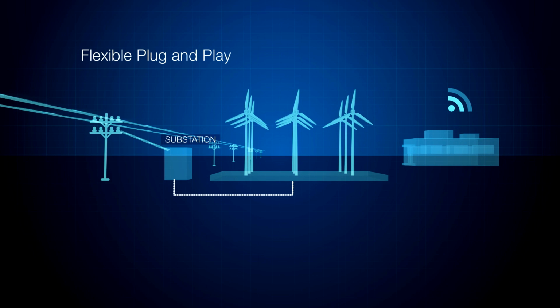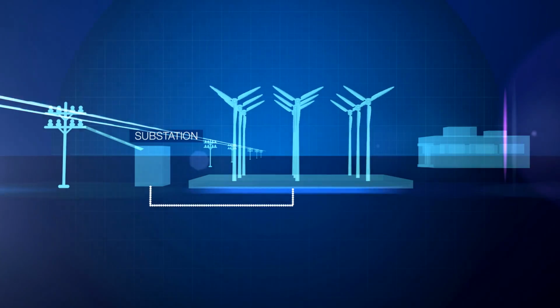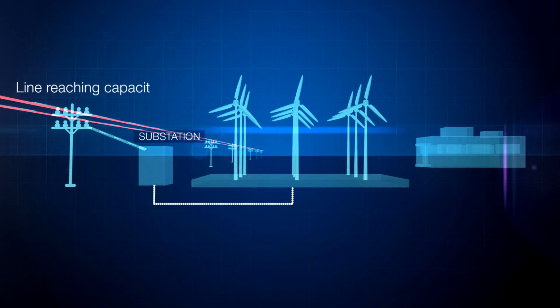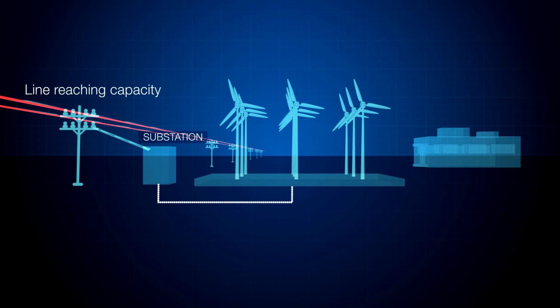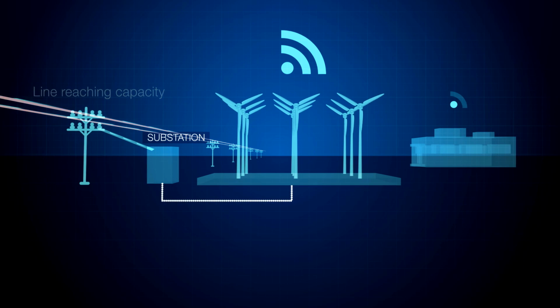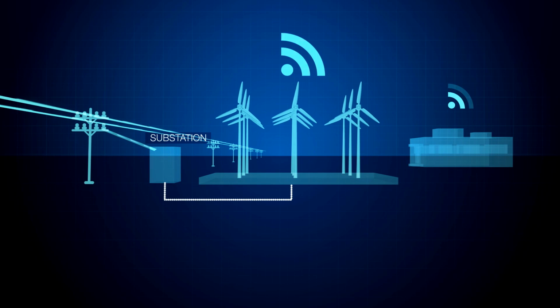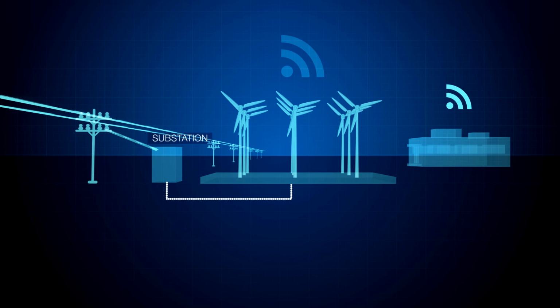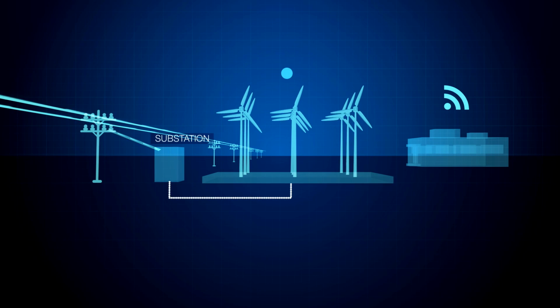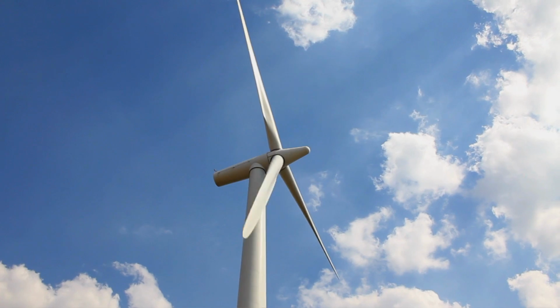So we've developed a commercial contract whereby the network operator has the ability to regulate the power output of the wind farm. So when we see the flow on the line reaching the operational limits of the line, we send a signal to the generator to reduce their output. UK Power Networks has committed to embed this innovation into standard business practices in 2015.